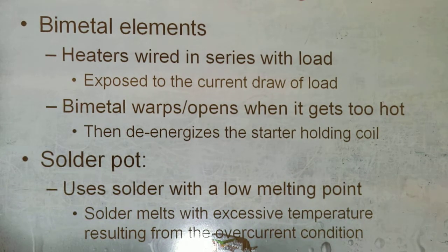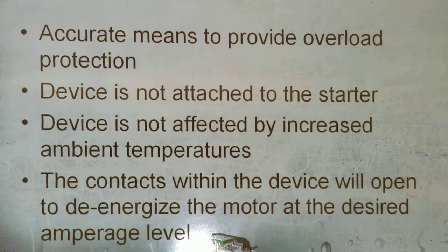Now, we'll talk about some other overloads here too. Magnetic overload devices. Accurate means to provide overload protection. Device is not attached to the starter. Device is not affected by increased ambient temperatures. The contacts within the device will open to de-energize the motor at the desired amperage level.